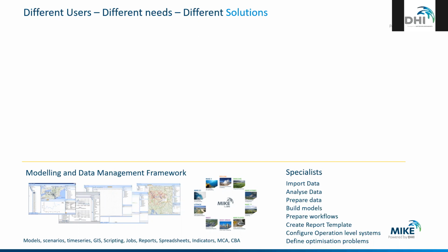You can then import the Mike models into Mike Operations and automate the picking up of that data and using it for boundary conditions and initial conditions for those models. And then you can schedule simulations at certain points in time of those models and automate that as a job process.